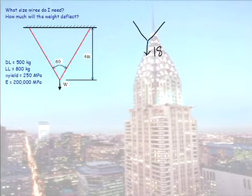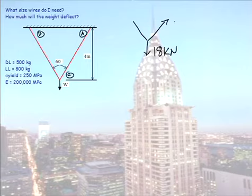My load down here is 18 kilonewton. I gave it the numbering system ABC. So this force here, FAC, force to the left, FBC. I'm drawing my unknown forces away from the joint. That indicates I'm currently assuming them to be in tension.